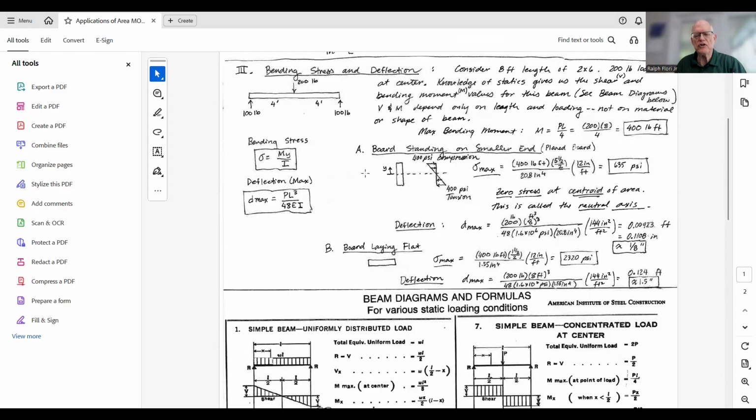That's one reason why I showed you the yardstick example. The same yardstick in one orientation resists bending because it has a large I in that direction, but the yardstick on its side has a much smaller I, and so it's very susceptible to bending. And remember, when the area is further from the central neutral axis, that results in a larger I.